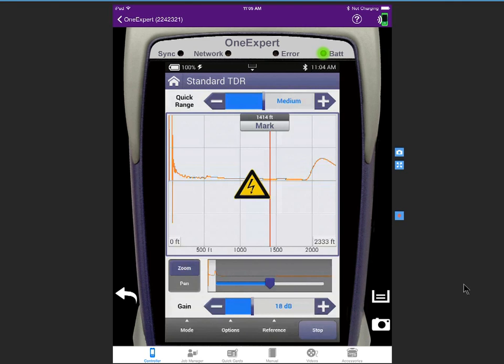Now, the DC source is a dual polarity source and a current limited one, meaning that it cannot hurt you or any electronic equipment that you may be measuring into or have on the line. The thought being is that the jolt of 120 volts might unsettle the line enough for you to catch a difference in the trace, because after the 120 volts has been applied for a few seconds, the TDR is turned right back on again. Well, to aid you in capturing that change in trace is the second half of this feature, and it's called peak mode.